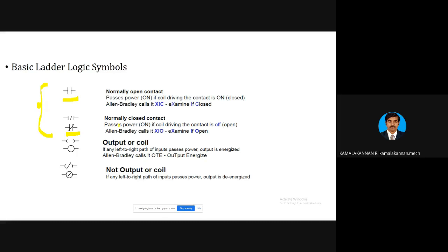But when you energize and give the input, this terminal changes its condition. When you have normally open, it will change to normally closed. When it is indicated as normally closed, it will change into normally open. Normally open is also indicated as NO. Normally closed is also indicated as NC. Again, I am telling you, a normally open contact doesn't have a contact. A normally closed contact means it is closed.